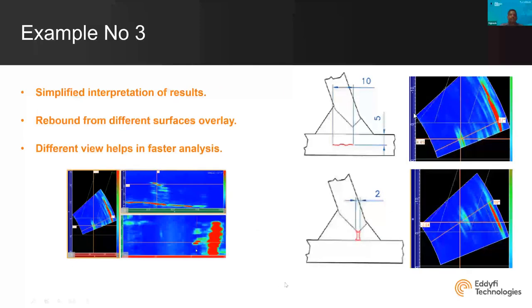Now, with the help of this, we can actually pick up indications, as you can see. So we had some sample plate and we tried to do some inspection here. And there is a defect over here, which is a tear basically. And this can be seen pretty much clearly here. So we send ultrasonic like this and we pick it up here.